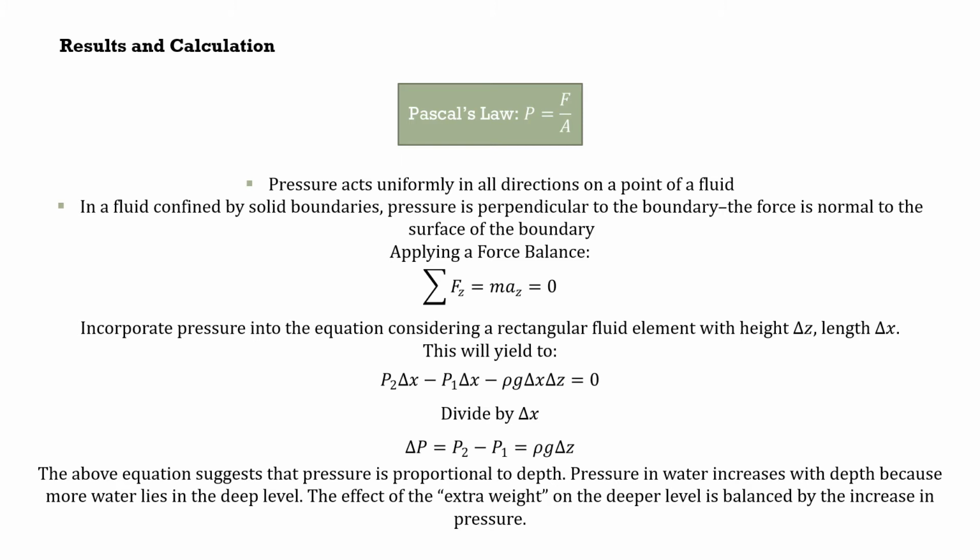Applying a force balance will incorporate the pressure into the equation, considering that it's a rectangular fluid element with height delta z and length delta x. The gravitational weight is the last term before the 0. So dividing by delta x will yield the change in pressure equation.